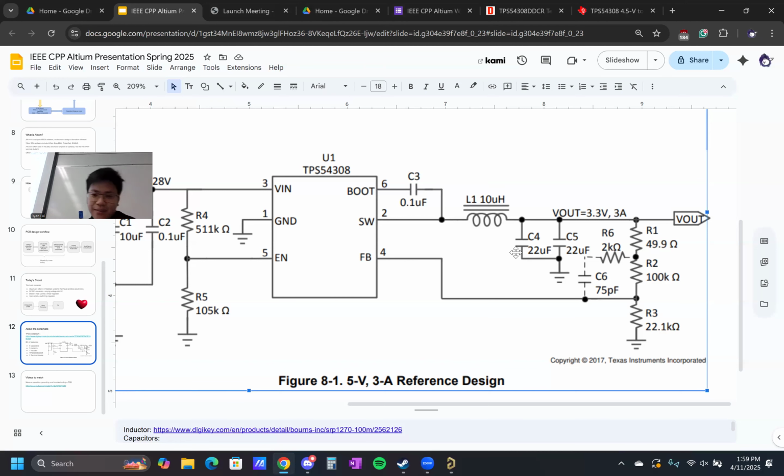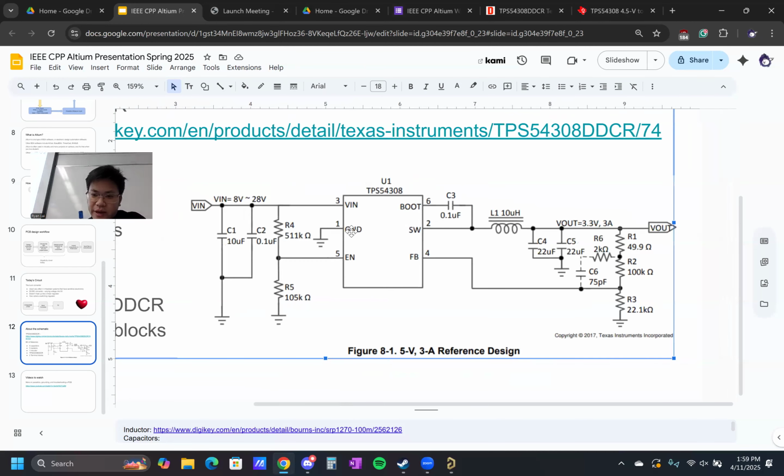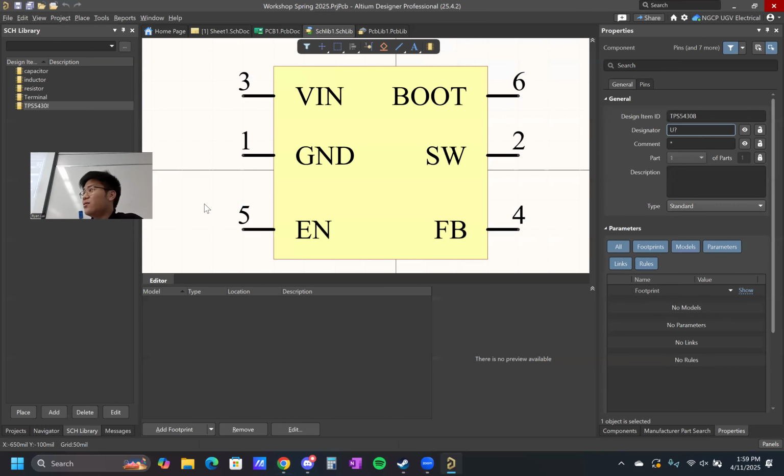Yeah. This is the schematic we're making today. If you want to change the voltage that comes out of this chip, you change this R3 resistor. I think the value is 13.5, which will give you a 5 volt output. But it seems like everyone's got it now.